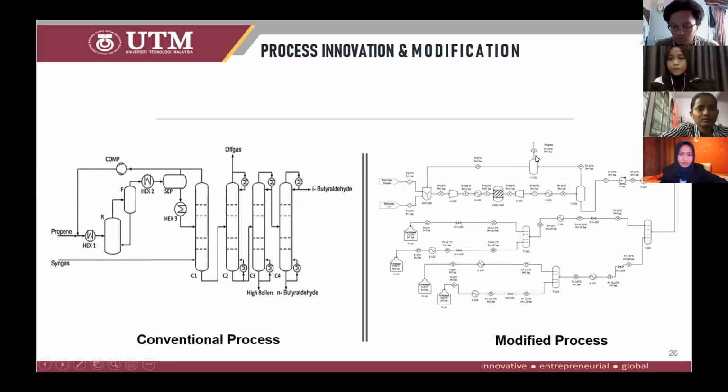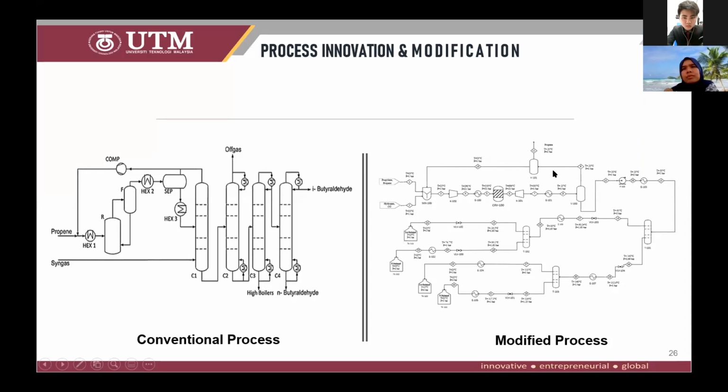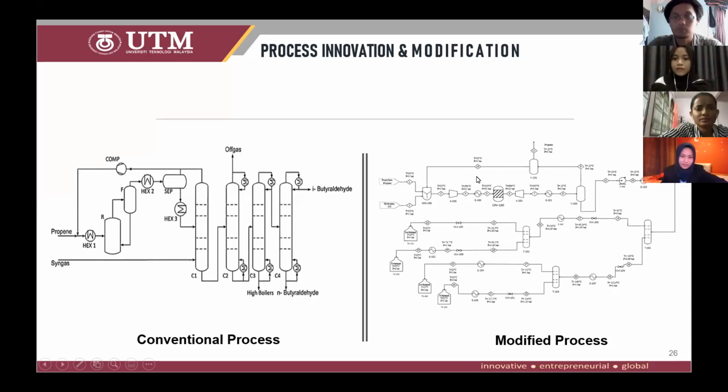As propane is our byproduct, it also does not involve any reaction. So to avoid any accumulation in our recycle streams, we decided to put a membrane separator to remove the propane before it is recycled back into the reactor. That's our modification. We add the membrane separator to remove the propane from our system.